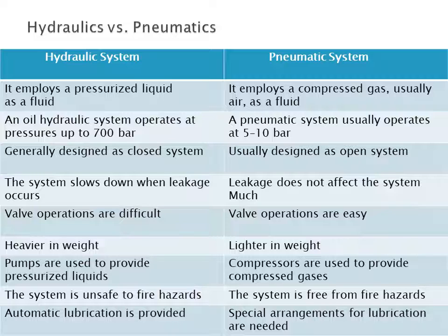Valve operations are difficult in the case of hydraulic system, whereas valve operations are easy in pneumatic. We'll see in the next slide how the valves are operated. Now, as I told you, the design of the hydraulic system is always complicated compared to the pneumatic system, and the hydraulic system is heavier, whereas the pneumatic system is lighter in weight. In hydraulic systems, we use pumps to pressurize the liquid, whereas in pneumatic system, we use a compressor to provide the compressed gases or air.